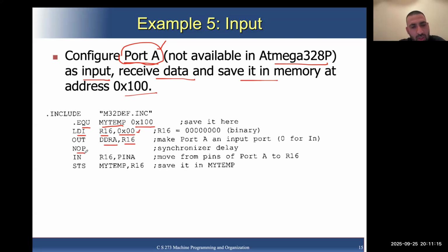And then we have a NOP instruction, why I will explain, but for the time being, just ignore it. And then we are saying, okay, read the value from PINA, which is basically, don't confuse it with pin A. It is basically the pin register of port A.